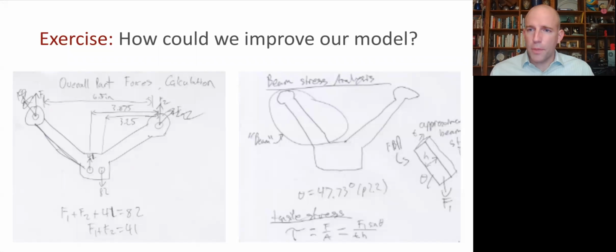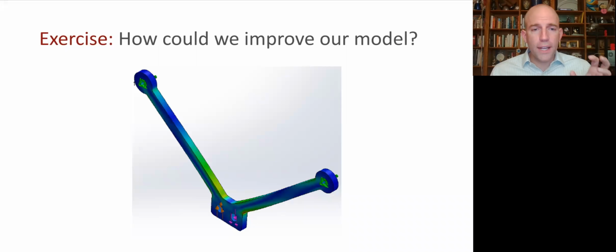If we look at the free body diagram this designer used, such as it is, we can see that indeed they were expecting those loads, I think it's clearest here, to be axial. And that turns out not to be correct. The finite element analysis did show us that there was bending if we look close. So if you look down here in the region where the part failed, we can see that classic bending pattern of stress, where on the bottom surface we have very high stress.